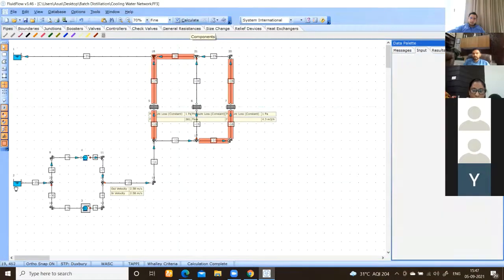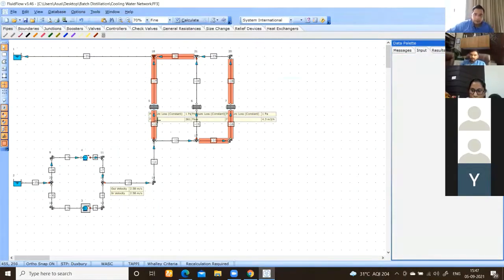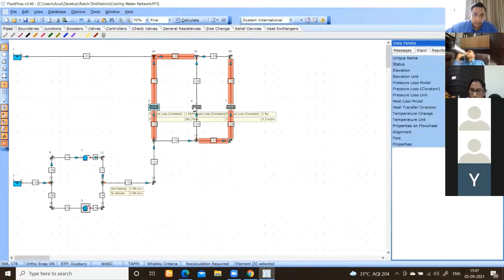All right, give me control. Given, sir. Check one. This is okay. Then pump, we are pushing 300. This is closed. This T I had told you to make on the left side. This pressure drop I set 1 bar, not 1 Pascal. That is the reason I had put this table so that we can easily find out.